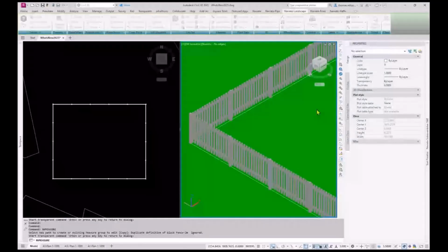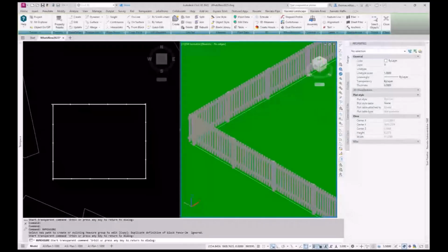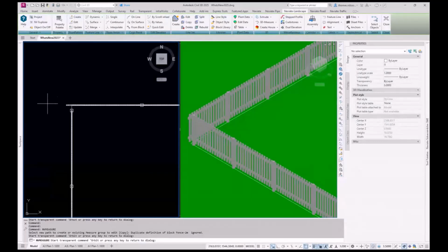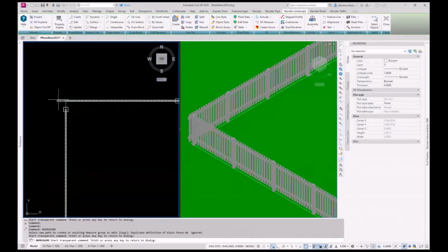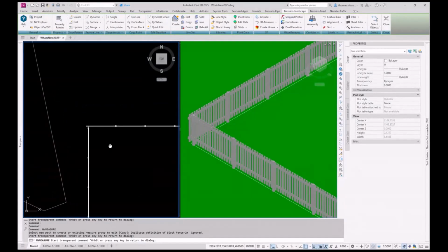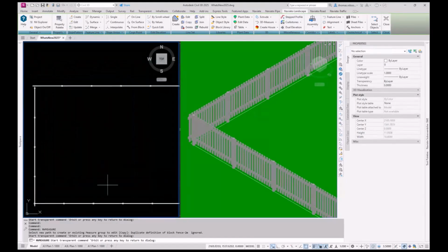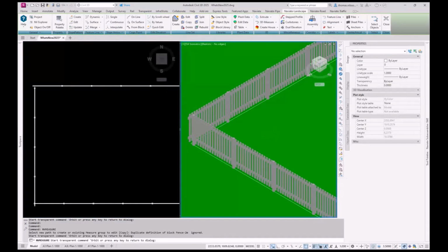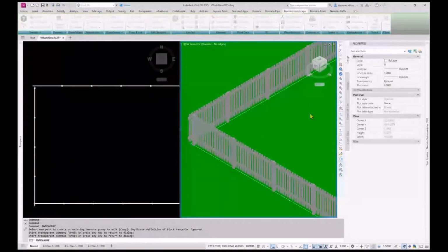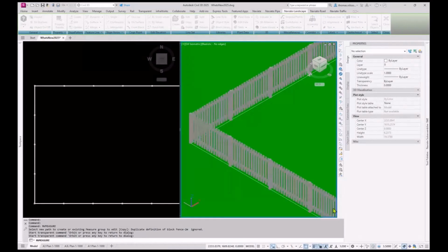If I do exact interval, you're going to see that it overlaps. If you look in 2D, we see it more. It's passing and then it starts there. It's passing here, so it looks a bit strange. But if I then set this even number by segment length, what it actually does is it adjusts the X scale, so they are a little bit shorter, and that's why they match perfectly.